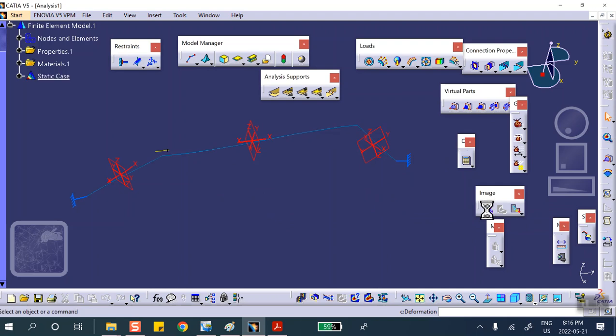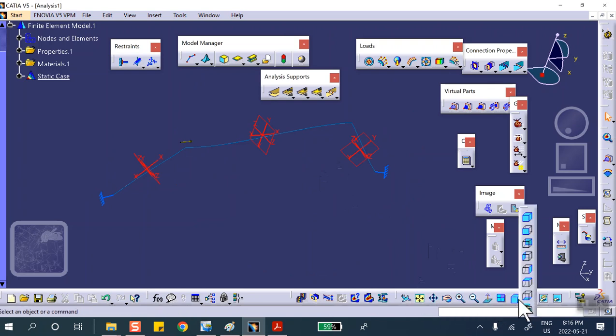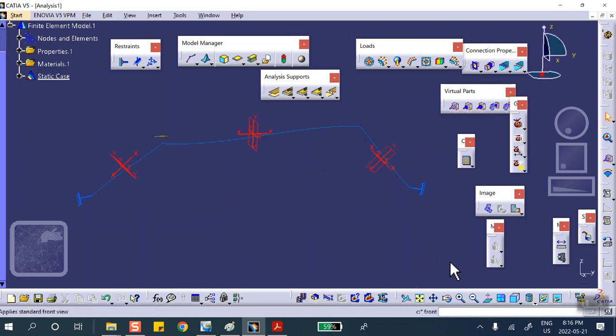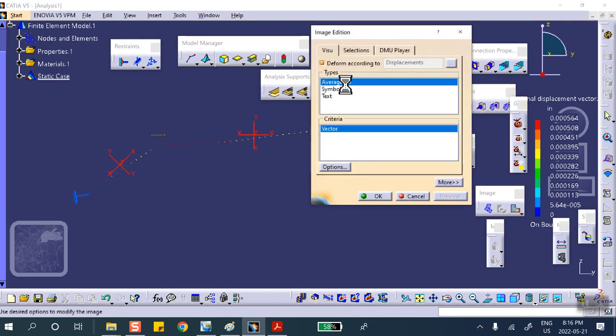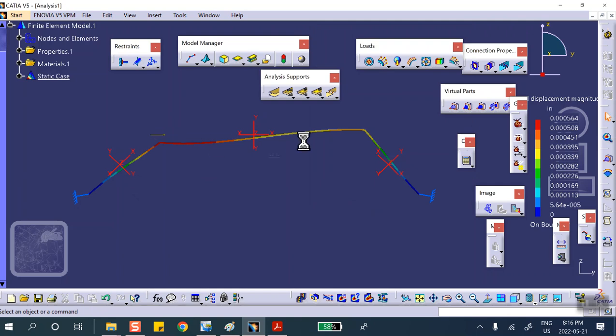The shape is going to look like that. You can see that. See? If you look at the view from the front, it's easier to see what's going on. There we are. Okay, so the original shape becomes like that. If you want displacements, you're going to plot the displacement and change this to average ISO if you want full color variation here. So pretty much it.